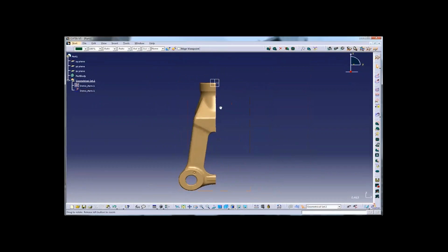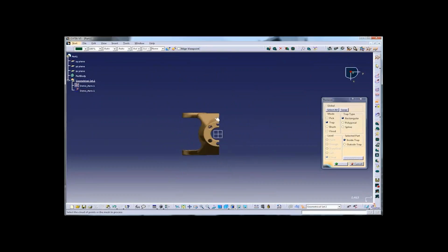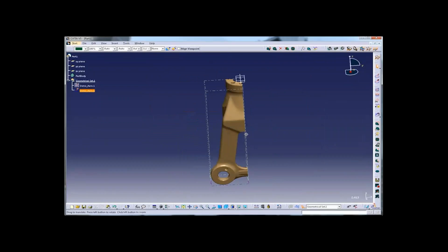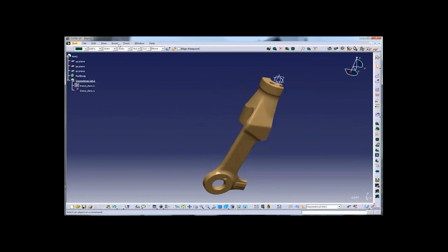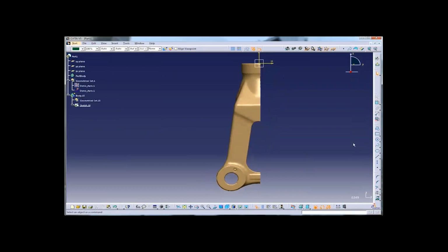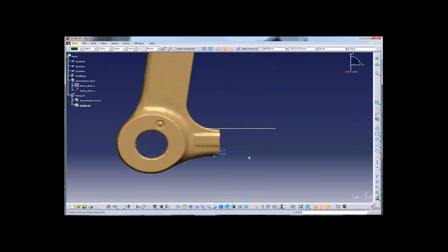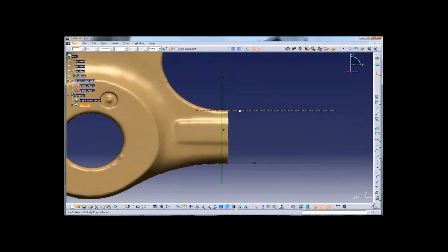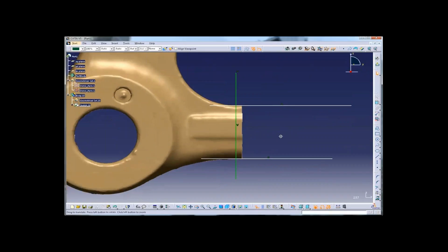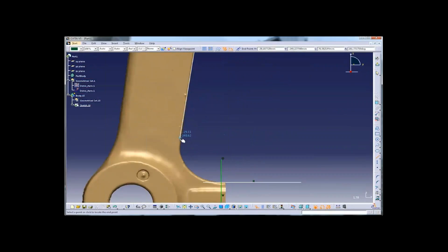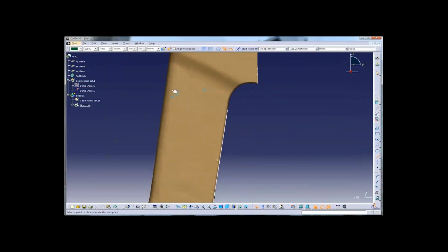Now, as the part is symmetrical, I can keep only a quarter of my mesh and base my design on it, so I'll then be able to create a mirror to get my final CAD model. So here we'll create the first sketch, or the first outline. I like to create different bodies and then just merge them or subtract one from the other at the end using Boolean operations.